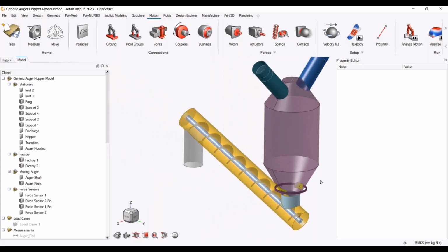The challenge here, the limitation with just using EDEM to solve this type of problem, is there's no way to set up the motions in EDEM. You've got the ability to define all kinds of different geometry motions, linear translation, rotation. You can input force controllers for both torque and velocity. You set up conveyor translation motions and things of that nature.